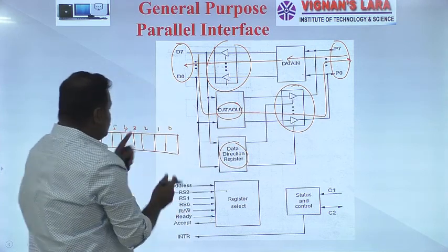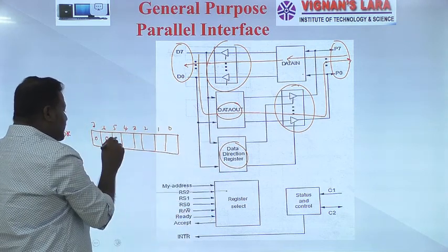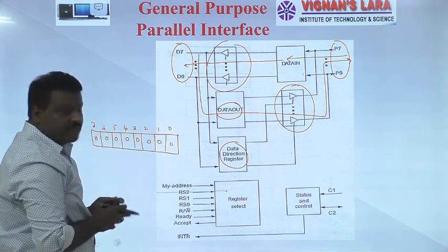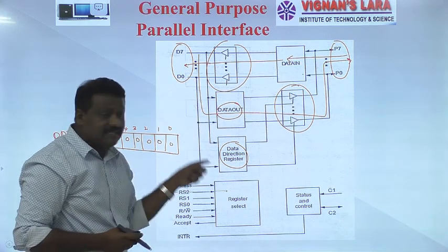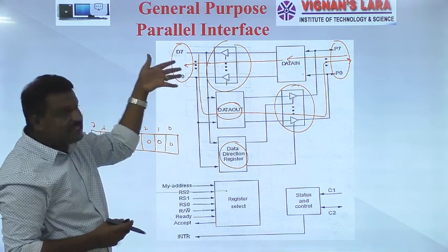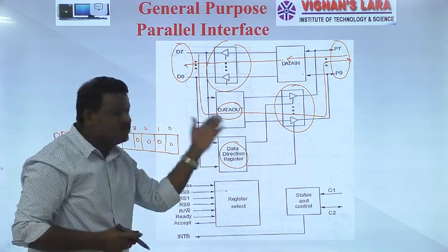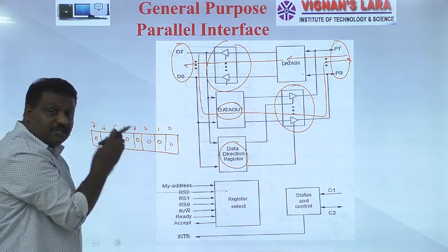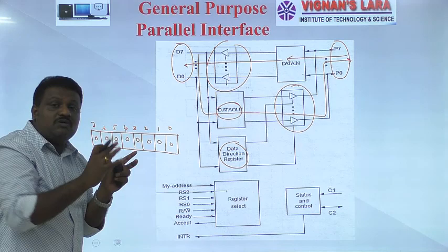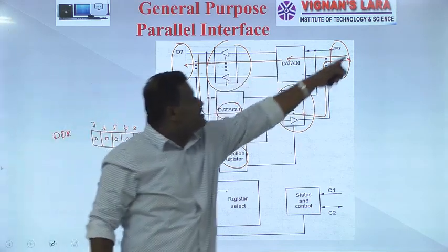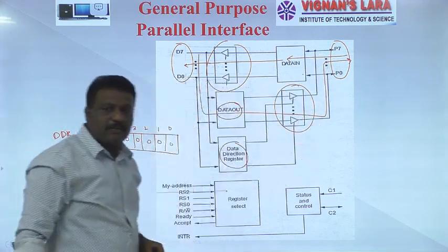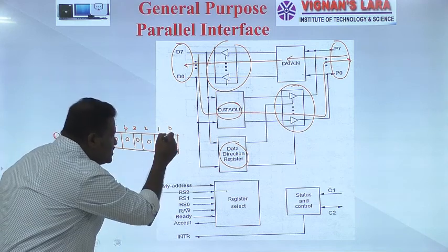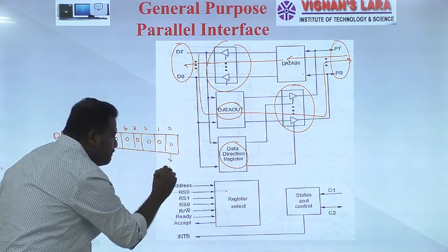So then what I can do is copy these values, set to 0, 0. That means my processor programs this data direction register by sending a command word that is copied onto this data direction register. If a data register's particular bits are set to 0, no doubt the corresponding signal here is made an input signal. For more clarity, this bit 0 belongs to PA0.